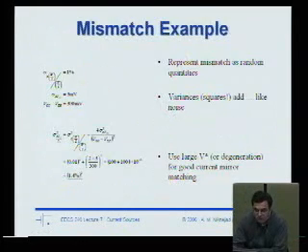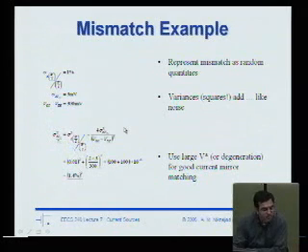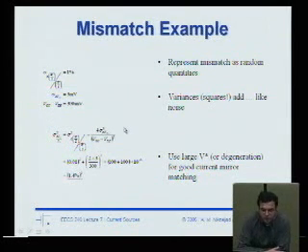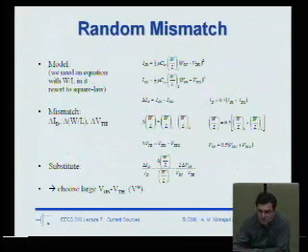So in reality, what we're interested in is the variance of the mismatch, a measure of the average mismatch that we get. They're random variables, so we don't sum up the standard deviations, we sum up the variances. So again, this is just this equation with each term squared.